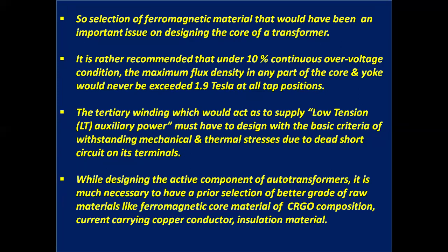While designing the active component of autotransformers, it is necessary to make a prior selection of better grade raw materials like ferromagnetic core material of CRGO composition, current carrying copper conductors, and insulation material.